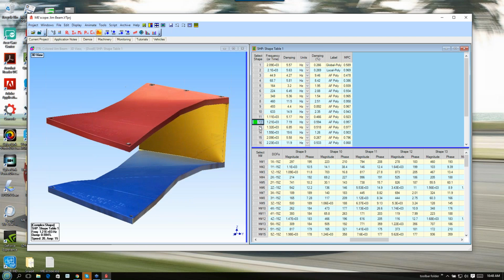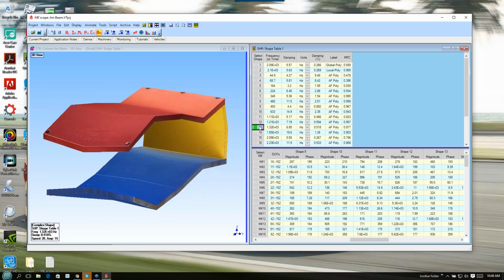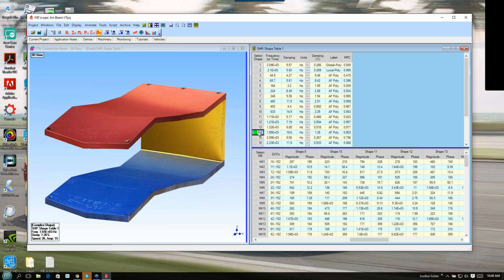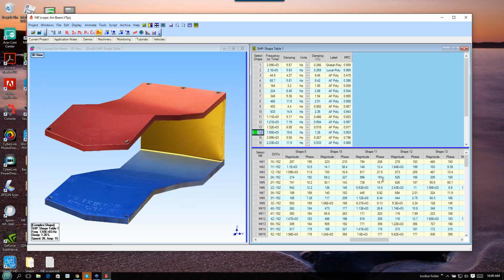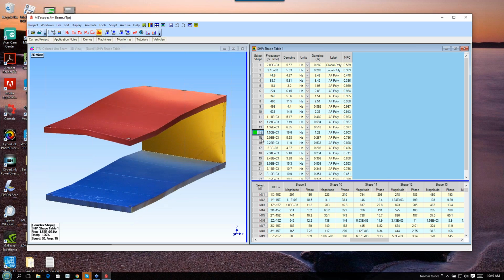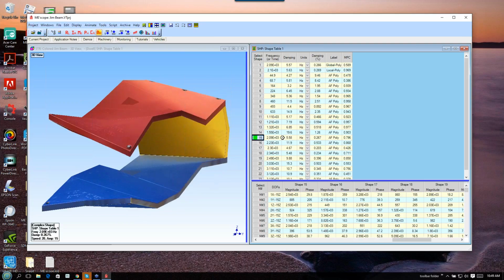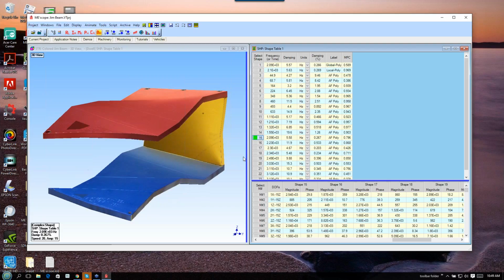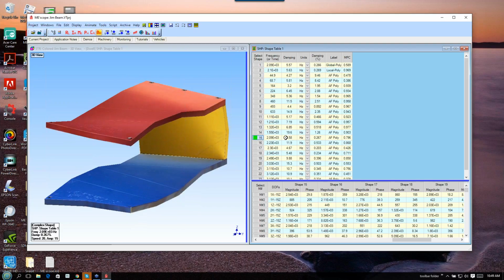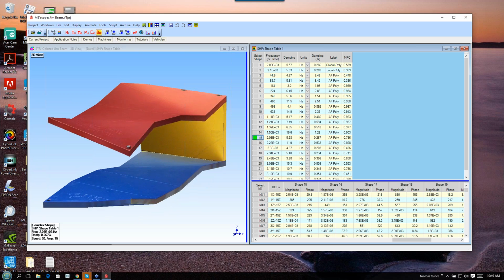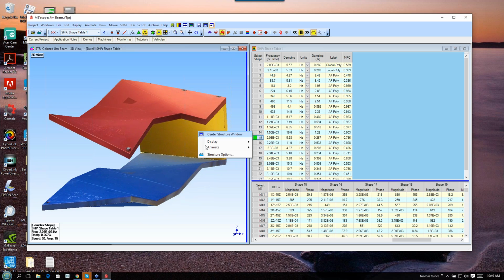Quick fit is really the easiest curve fitter to use to get familiar with your data, but you can see all these mode shapes are coming out very, very clean. There's not a lot of complexity. Here I get up to the one that we were fitting before, the 2000 hertz, and it's got 5.59. That's roughly what we got from the local fitter, but you can see there's a lot of complexity in there.